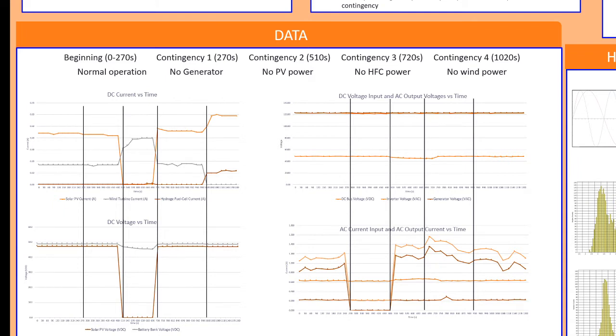They're going to stay steady unless you really do something bad to them. What will instead change is the current whenever you mess with a generator. So since I took it out of the system, it dropped to 0 amps. It's still reading 120, that's just how I had the meter set up. But the current dropped to 0 amps, and the generator current is this guy right here.